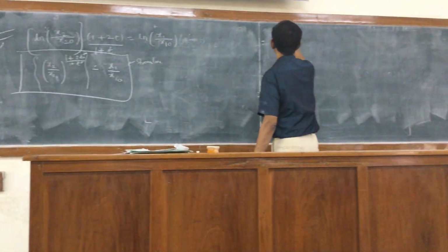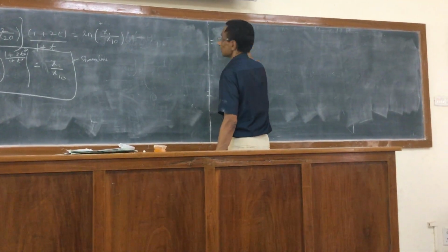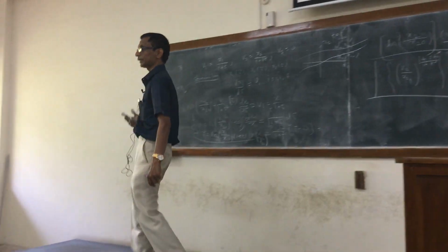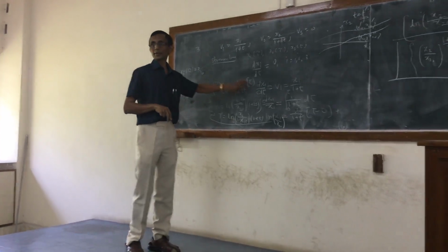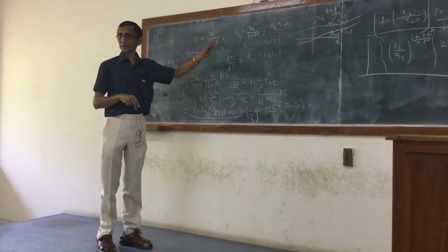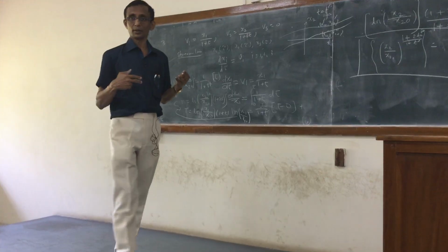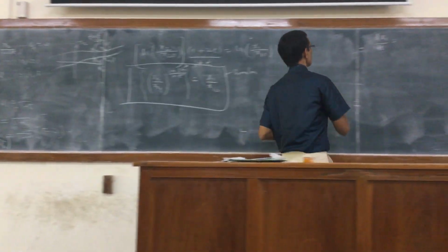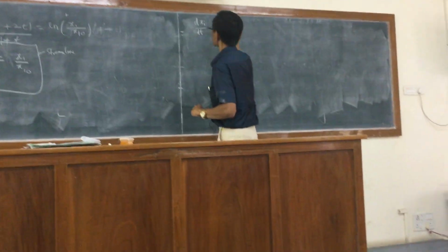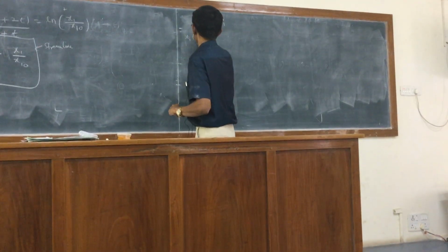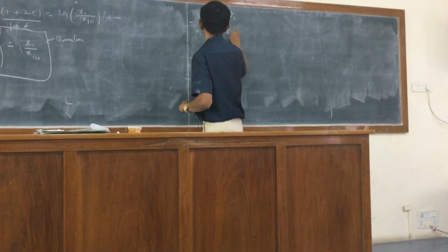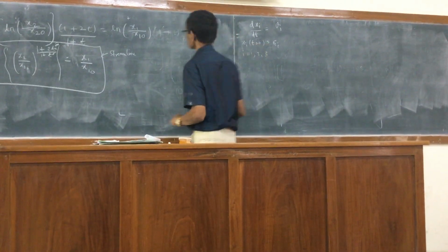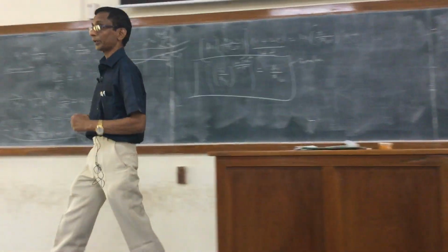So that is dxi by dt. dt now comes into play. This is the particle path. We are directly dealing with the velocity. There, we are looking at the velocity as a tangent to the streamline. That's why the equations, even though they look very similar, have quite different meaning. Now what about the particle path? The particle path will be dxi by dt equal to vi, and then here, xi at t equal to 0, I call it psi i, i equal to 1, 2. And here the integration is with respect to time.